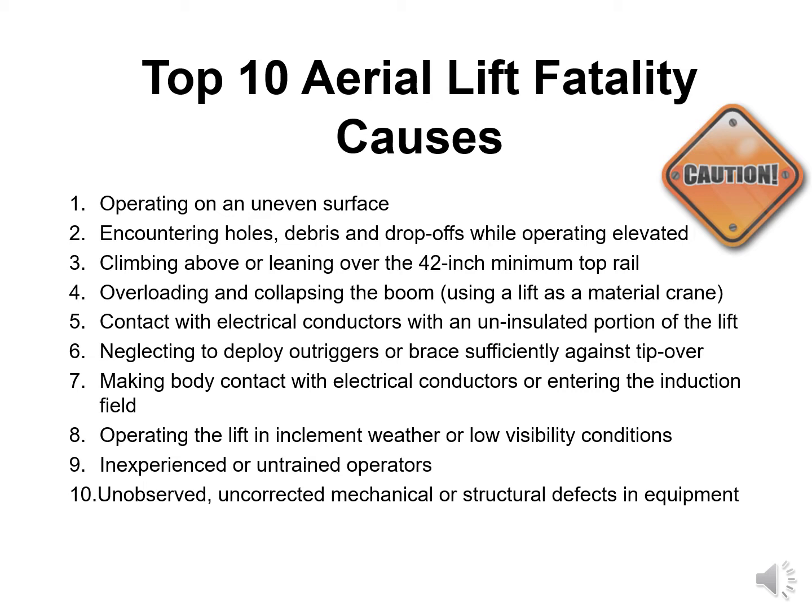5. Contact with electrical conductors with an uninsulated portion of the lift. 6. Neglecting to deploy outriggers or brace sufficiently against tip over. 7. Making body contact with electrical conductors or entering the induction field. 8. Operating the lift in inclement weather or low visibility conditions. 9. Inexperienced or untrained operators. 10. Unobserved, uncorrected mechanical or structural defects in equipment.